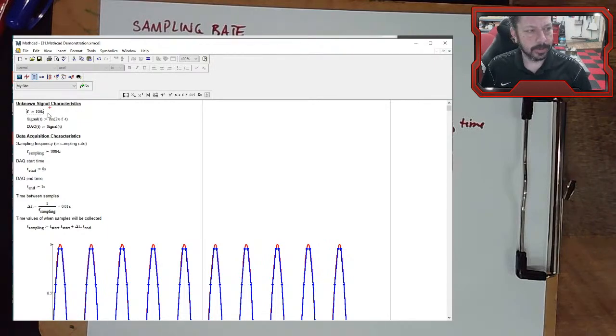We're not going to talk a whole lot about filtering, but there are digital and analog filters out there. You can build filters with op amps, you can build them with resistors and capacitors, you can build them into software to filter them out, because what will happen is that unwanted 60 hertz signal, if I only want 10 hertz, then the 60 hertz could alias down to a 10 hertz signal, or it could alias to something that interferes with what you're doing.